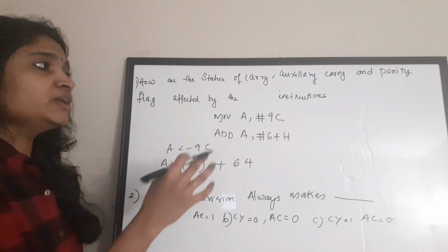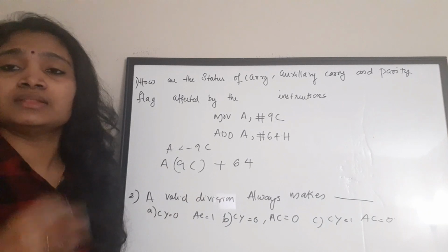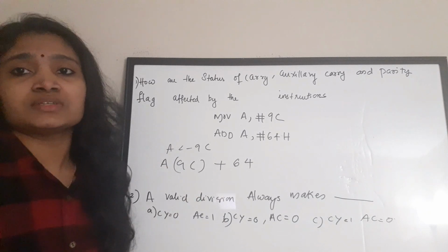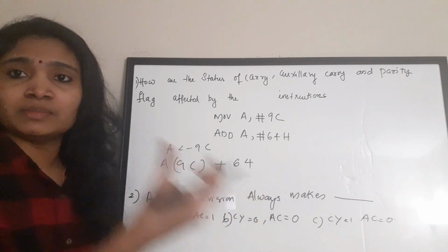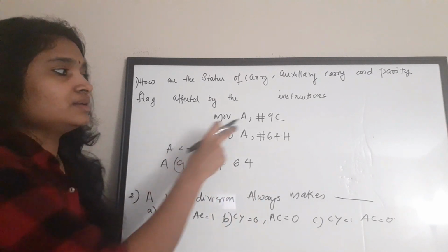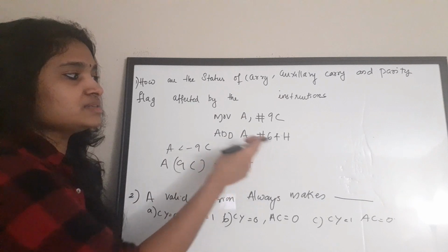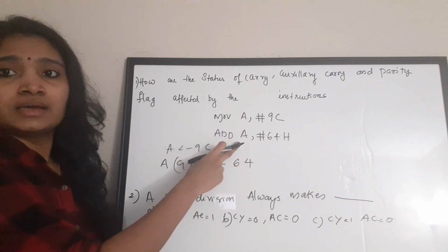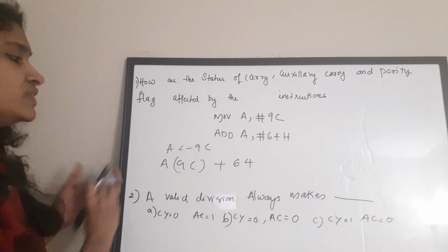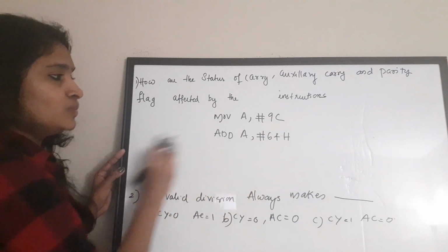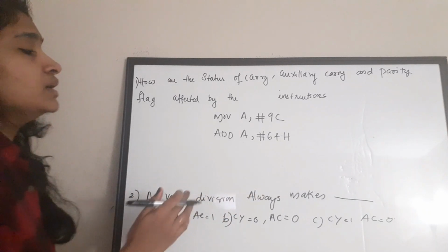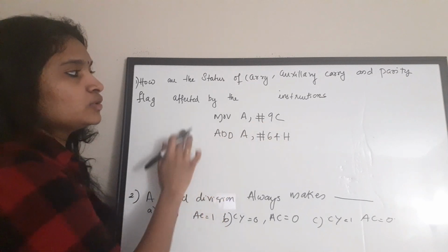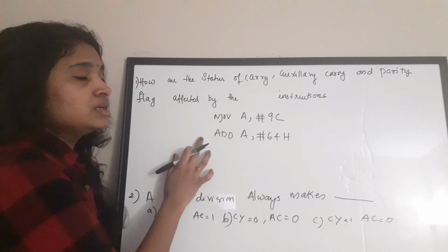You should know the very basic programming things to answer these types of questions. Hash means an immediate value, that is, a number directly moved to that register, and then this number is directly added with the content of the accumulator. While discussing these questions, you will get familiarized with these basics. The actual result is not the question.